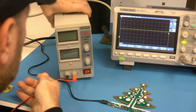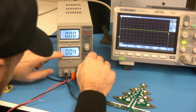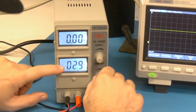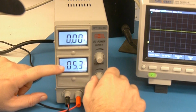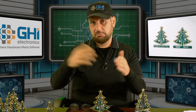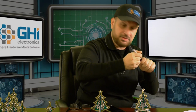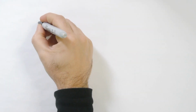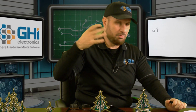So what I did then is grab my trusty benchtop power supply. Instead of using USB, connect the power supply to the tree, and then try different voltages. Sure enough, when we go to 5 volts or more, the lights will not work anymore. Go below that, and they would start working beautifully. Let me write down what I noticed because we're going to need this later. At 4.7 volts, everything worked beautifully. Anything above that, we had a problem.